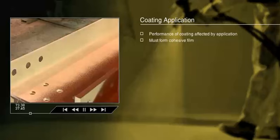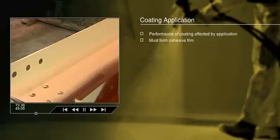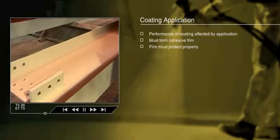To become a successful protective coating, the material must be transferred from its primary container to the surface that is to be protected and must then form a cohesive film with desired properties. The film must be dense, resistant to the passage of moisture and other potentially damaging or corrosive materials, and must dry or cure to its solid state. The application process plays a significant role in the film formation process.